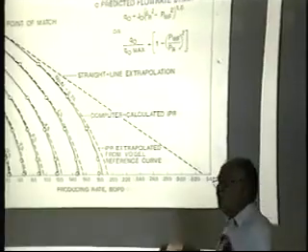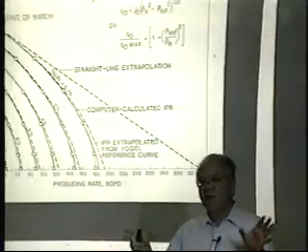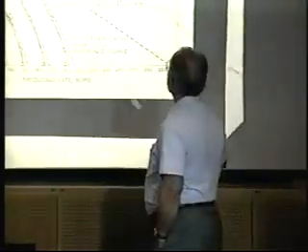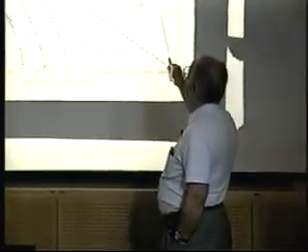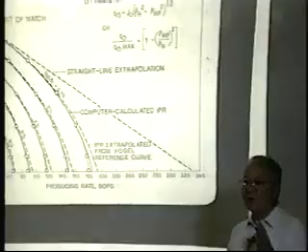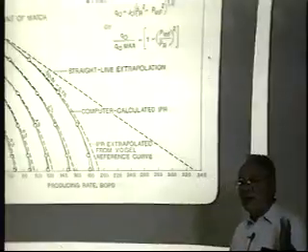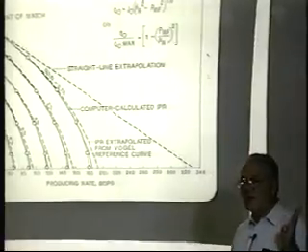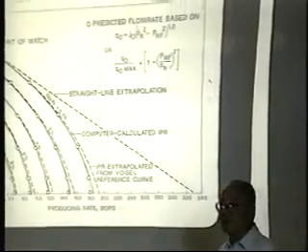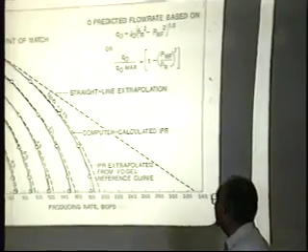The slope of 1 is very close to the Vogel equation. So if you use this or Vogel's, you get about the same results as a production engineer. But as a reservoir engineer, I need to do more. In this form, I dropped the 1 term, and the coefficient becomes 1 for the squared term, and the other coefficient becomes 0. Now I have a back pressure equation where, like I said earlier, the rate's not strongly a function of the level of the flowing pressure that I'm going to choose. So that's one advantage that I have in knowing it behaves like a gas well.